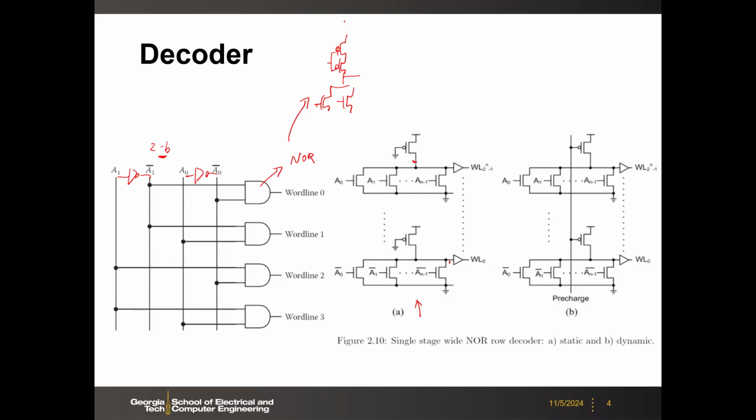If you do a fully CMOS version, that will bring a lot of overhead. So one alternative design is to use just a single PMOS as a load. Of course, then the pull-down is still parallel NMOS. But the PMOS here is a PMOS load that always turns on. So this will not be fully rail-to-rail logic. There will be some static power consumed by this circuit.